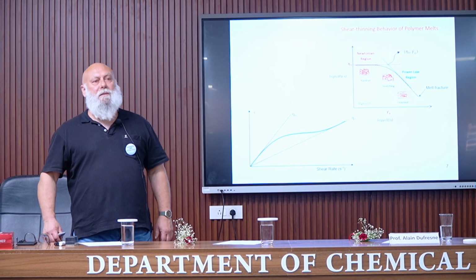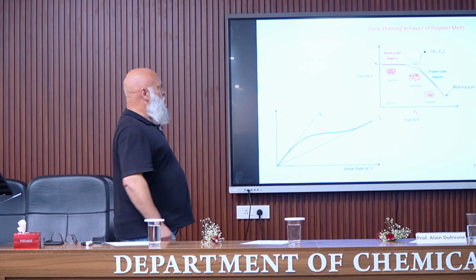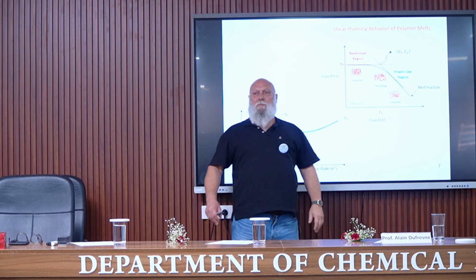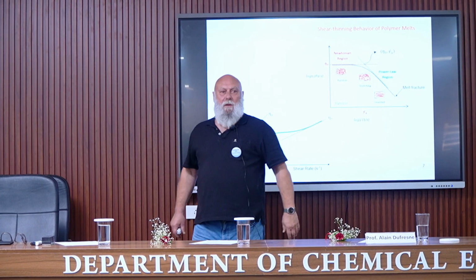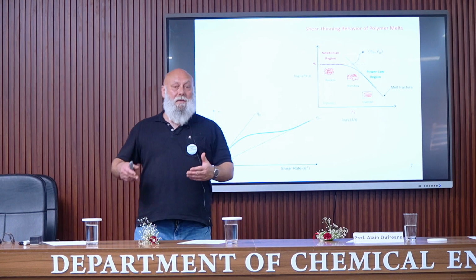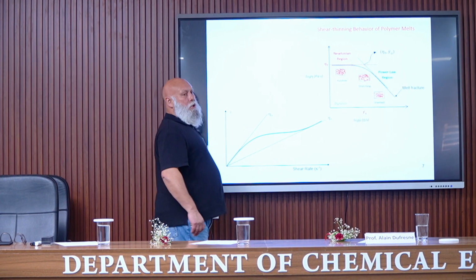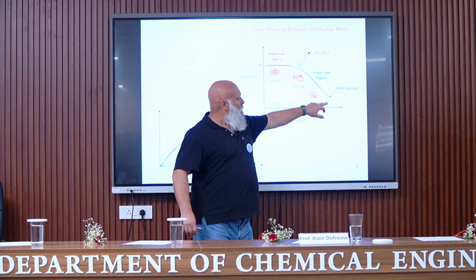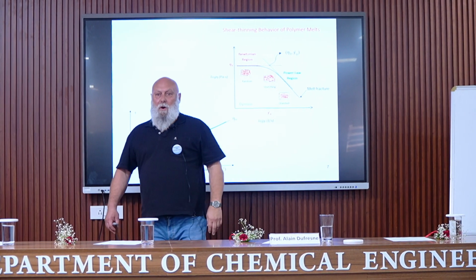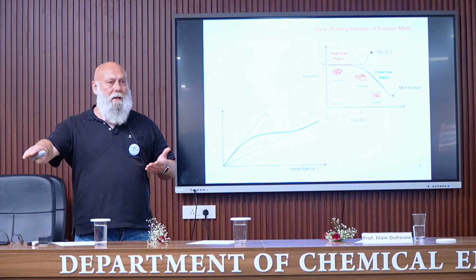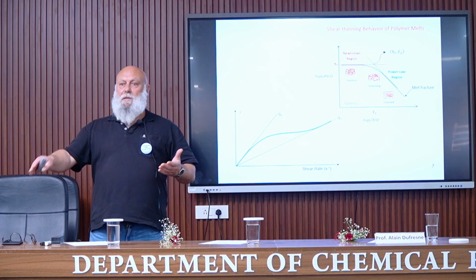When increasing the shear rate, we can have a permanent orientation of the macromolecule and then a decrease in the viscosity of the material. What we should observe is a second stabilization for higher shear rate, because when the macromolecules are completely oriented, the viscosity should not change anymore. But we cannot observe this second plateau.